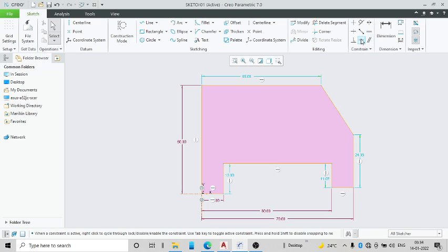Okay, let us go for coincident. Say I want this point to be coincident on this line. So you go and select the coincident. My intention is to make this line and this point lie on a single line, because this particular edge is locked, this line is moving here and there.